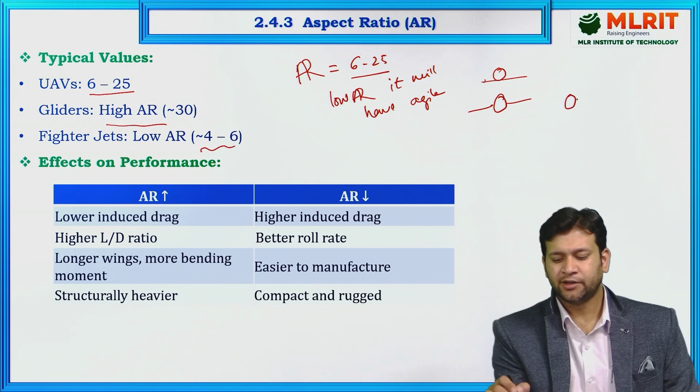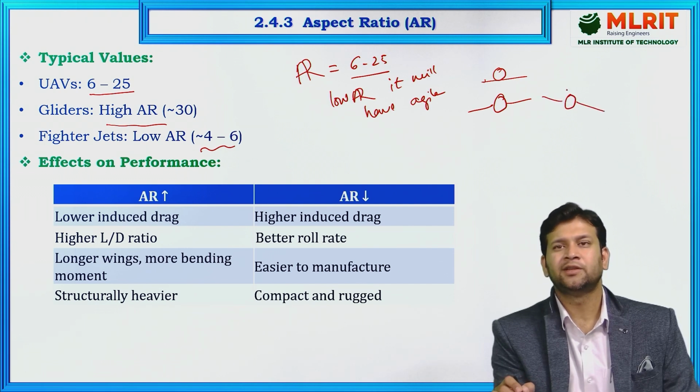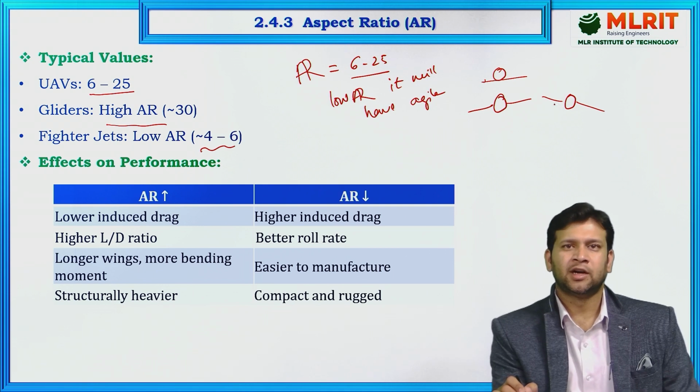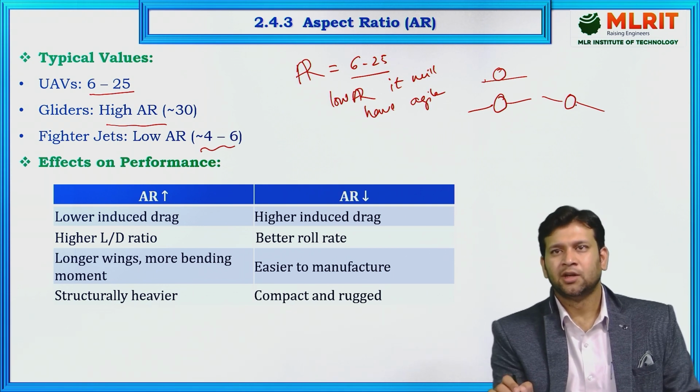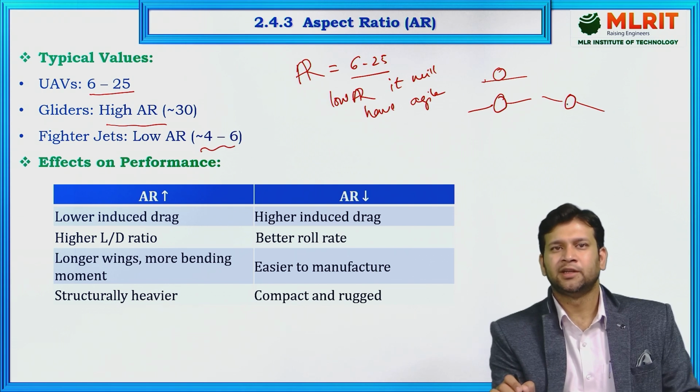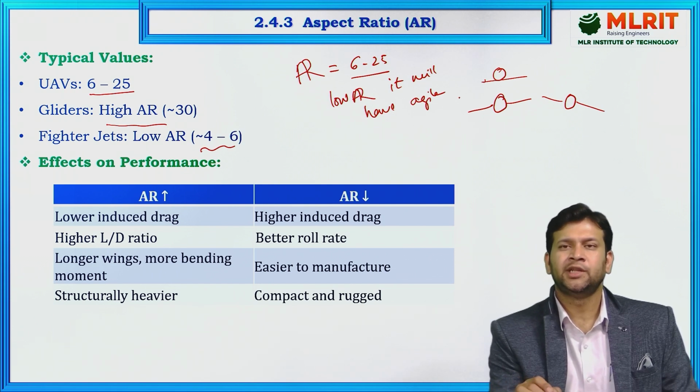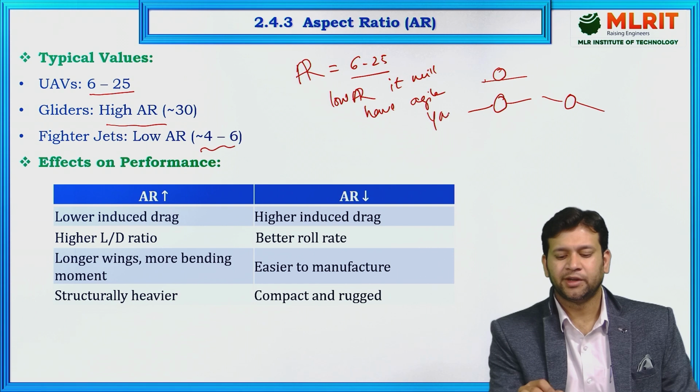It will just change like this in order to change the direction. It doesn't roll completely, but yes, there are control surfaces which can ensure that it can roll. But because passengers are sitting inside, to ensure a smoother flight, it will just bank left and right for changing the direction of the flight, and the other aspect is yawing.